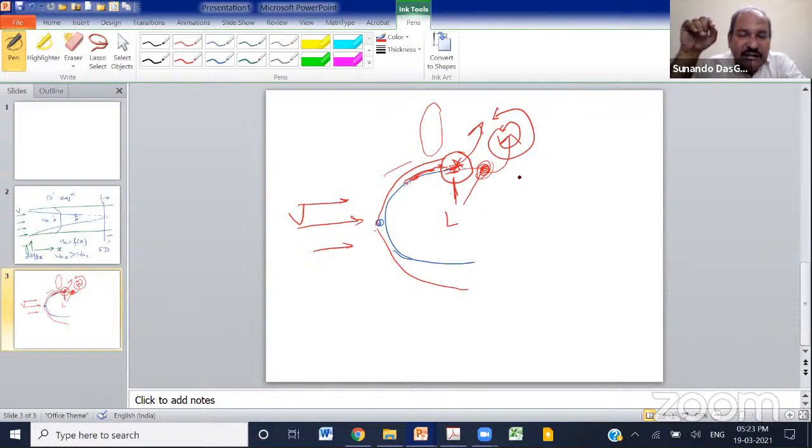Since the golf ball has dimples, turbulent flow and less drag acting on it, it will move further as compared to a normal ball of the same size and weight, but without any dimples on it. So that's a practical example of the delay in the onset of boundary layer separation by creating turbulence upstream.